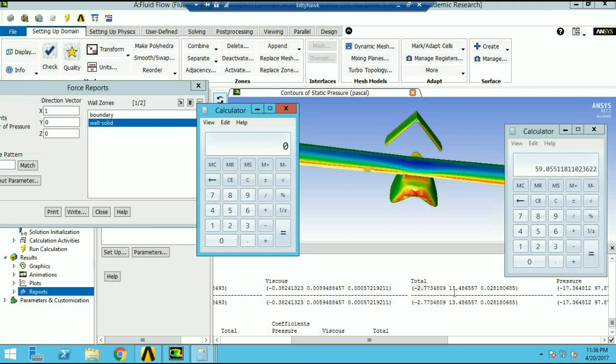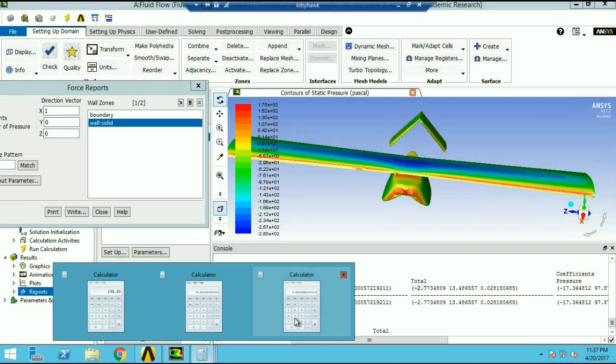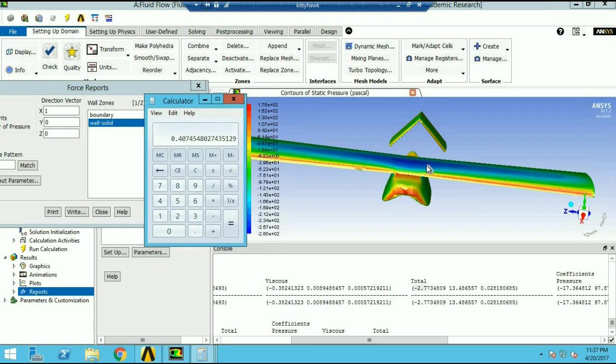We start with the lift, so 13.48 pounds divided by Q, so divided by 0.5 times 0.002376 standard density, times V squared, so 59 times 59, and then divided by S, which is 8 feet squared for this aircraft, so divided by 8. And we get a lift coefficient of about 0.4, which is pretty good. Cruise should be around 0.3 lift coefficient, so 0.4, pretty accurate.